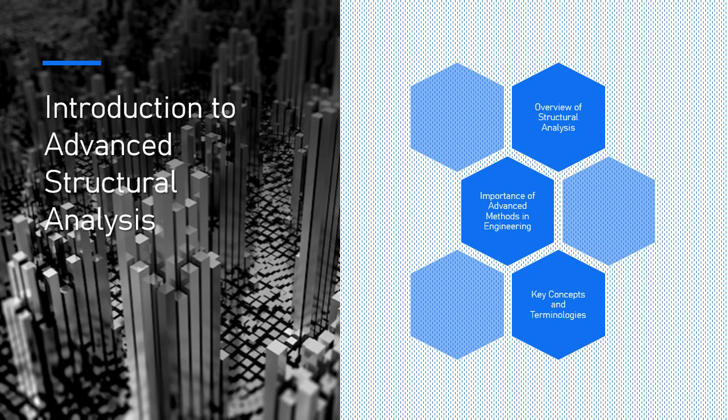1.2. Displacement. Displacement refers to the movement of points on a structure due to applied loads. It's essentially how much a structure deforms, bends, stretches, twists, in response to forces. Displacement is crucial because it indicates serviceability. Excessive displacement can lead to serviceability issues, such as cracks in walls, non-functional doors, or windows that no longer align properly. In some cases, it may even compromise the building's aesthetics.